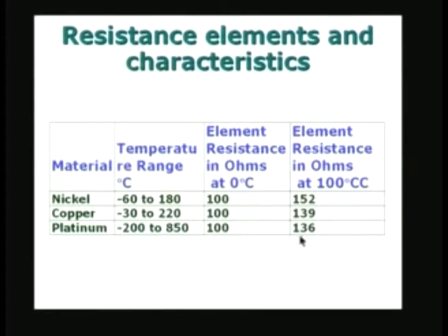like 100 to 136. The main difference between resistance thermometers and thermistors, which we will see later, is that this variation of resistance is very small in the case of resistance thermometers, and the resistance increases with temperature. In the case of thermistors, it is going to decrease with respect to temperature and also decrease by a larger fraction. And therefore, thermistors are more sensitive, but they have a smaller range compared to the resistance thermometers. The case being, we are talking mostly about the platinum resistance thermometer.